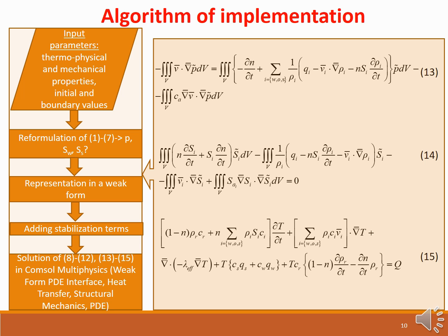The last step is the implementation of the obtained equations into COMSOL Multiphysics using the weak form PDE interface. The energy balance equation was reformulated in the form 15 and solved in the heat transfer module. The mechanical part of the model was solved in the structural mechanics module. Constitutive equations for damage accumulation were implemented in COMSOL using the coefficient form PDE interface.